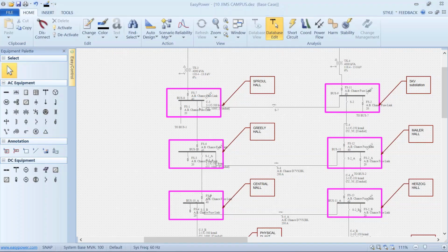Okay, appreciate the questions. It looks like I've stomped all over a few of them. And if you have any other questions, I think, John, you asked the question, the difference between drawings and name views, and I think Kay just pointed it out to us. Name views will keep up with changes because it is the one-line diagram, whereas drawings are a snapshot, and if I make changes to the one line, I need to recreate the drawing that's being saved.